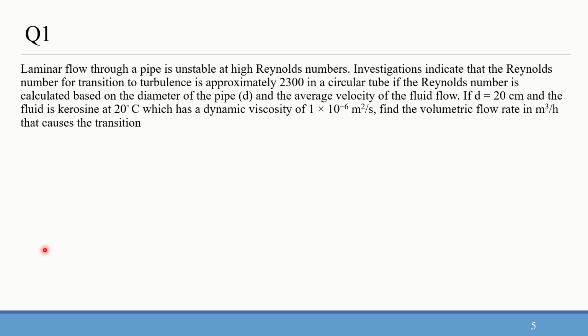So as we all know, the Reynolds number calculation is on several bases depending on the type of Reynolds number which we are calculating. If it is a particle Reynolds number, it is basically rho into V into characteristic length divided by mu. Rho V L by mu, rho V D by mu, whichever. For pipe flow, that is with a circular cross section, we will be using rho V D by mu, where D is the diameter of the pipe.